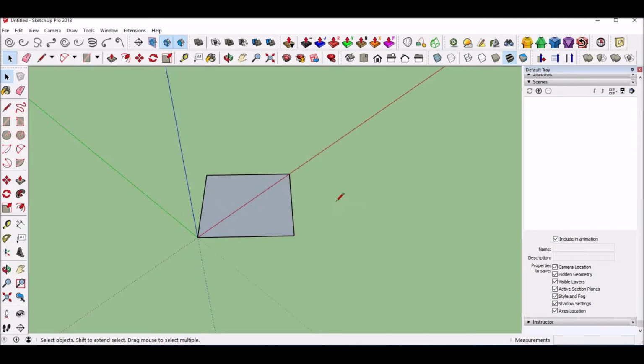Okay? Now my axis goes straight through here, and the reason why this makes it convenient is because if I click here, I can run it right along that point, type in 60, and we're good. Come over here, hit escape to let go of that point, click here, and notice when you get up close to it, you'll see that green line appear and the two dots show. That means we're constrained to that point. And there we go. Same part. So, two different ways to accomplish the same thing.